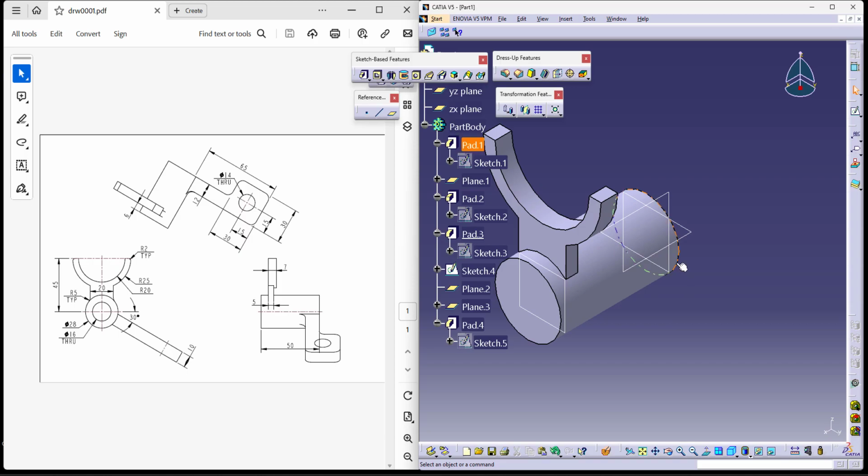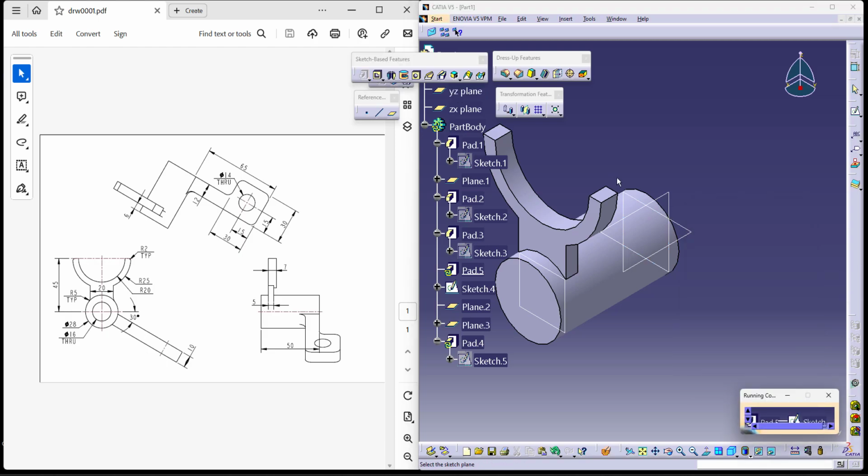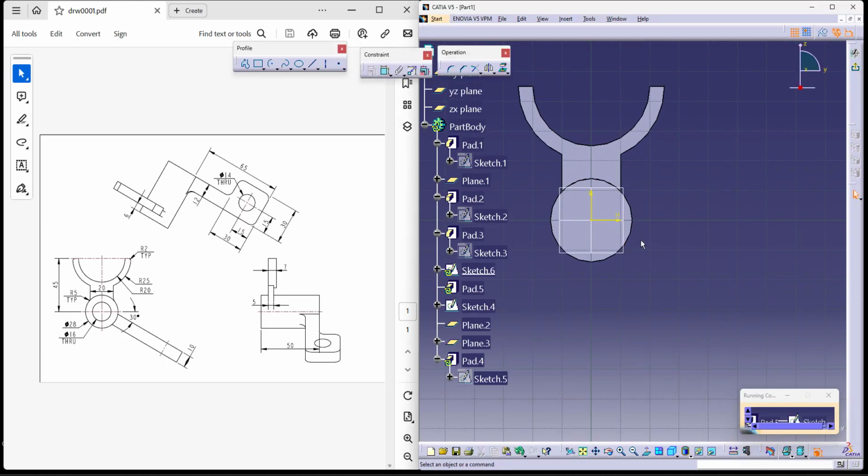The other method of doing this is by using the back face as my reference, which as you can see, the plane is my reference. On this plane, I'd like to make a 30-degree angle and then try to create the angled rectangle this way.